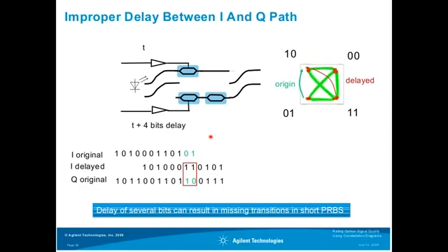And then let's take a look at the constellation diagram. The original constellation at this point should be a 0,1 to a 1,0 transition. Here we have the 0,1 and the 1,0. But when we shift this, in this case by 4 bits, then this translates to a 1,1 to 1,0 transition, which represents this kind of transition. Here's the 1,1, and here's the 1,0.